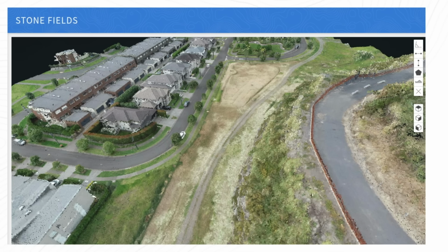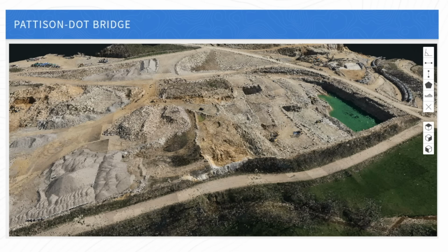So generally what we recommend is, if you want to get building facades, if you want to model those well, we recommend capturing imagery with an off nadir angle of about 30 to 35 degrees. Because if you go too far off nadir, the overall quality of your point cloud does start to degrade.